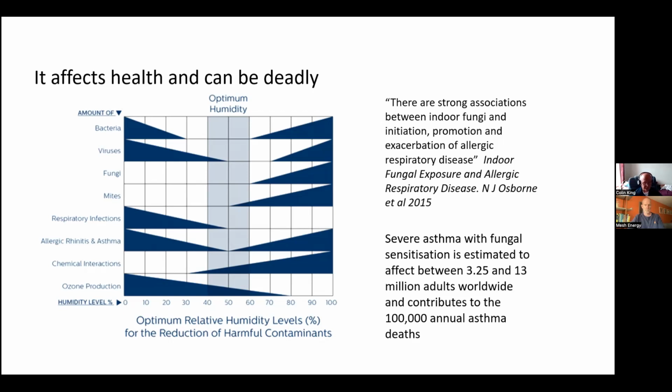When we get round to actually having smarter homes with intelligent energy systems and in-house monitoring, we will be in a better position to ensure that we achieve these correct levels of relative humidity, and actually start looking at VOCs and other things which affect indoor air quality, because that's really what Part F is trying to deliver, good indoor air quality. But you can see that this band where we're at our healthiest, if it's too dry, it's not healthy for us. If it's too moist, it's not healthy for us. It's this zone where we as humans actually perform the best.